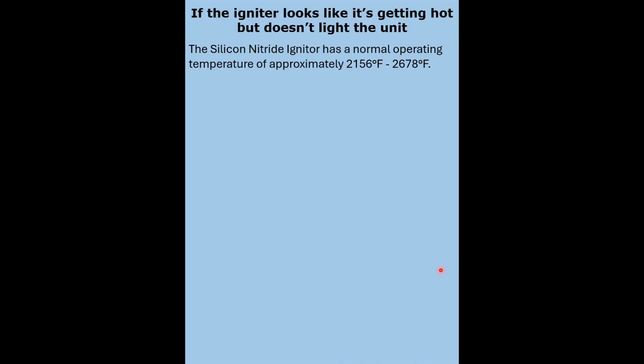operating temperature of approximately 2,156 degrees Fahrenheit to 2,678 degrees Fahrenheit. At room temperature, the igniter ohm reading should be from 37 to 68 ohms.